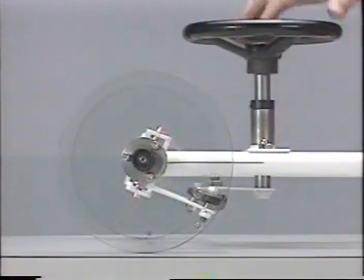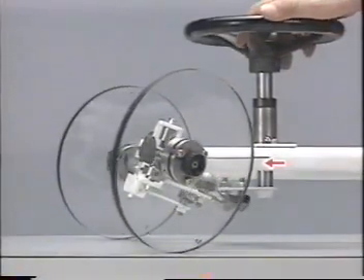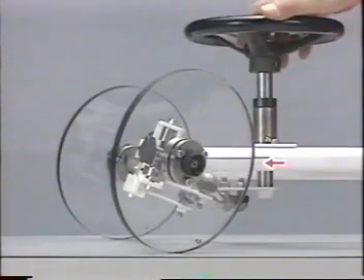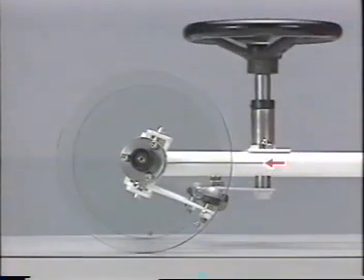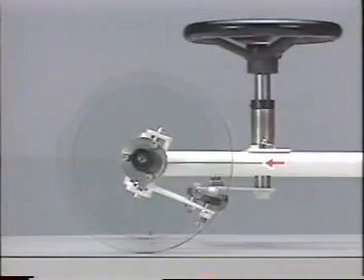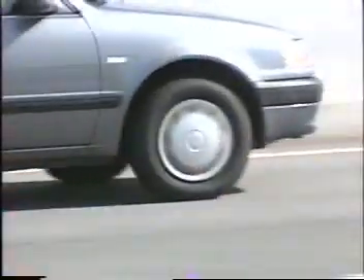With a caster angle, on the other hand, when the steering wheel is turned, a jack-up torque is generated at the wheel on the inside of the turn, raising the car body. If you release your grip on the steering wheel after turning, the weight of the car applies wheel recovery force, and the steering wheel swivels back to the straight-ahead condition where the moments on the left and right wheels are balanced. So as we have seen, positive caster and caster trail contribute to straight-ahead stability and wheel recovery after turning.